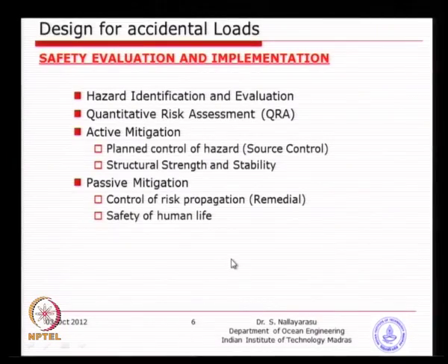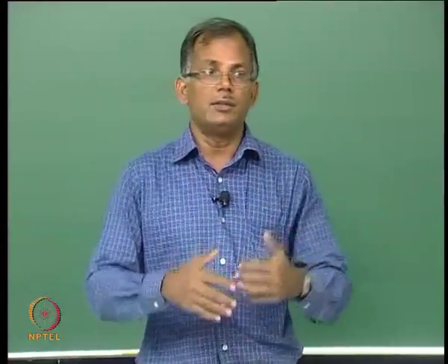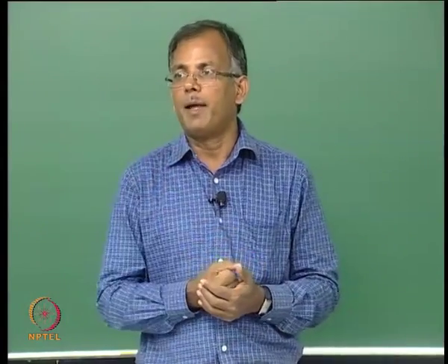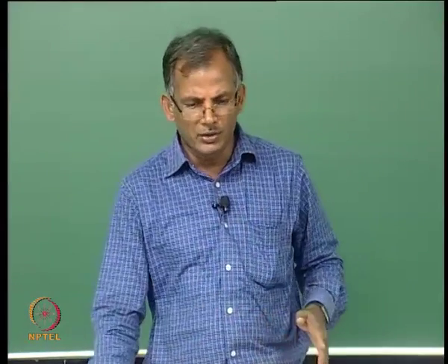And so, before we go forward towards trying to design, we need to identify the hazard. Hazard is nothing but something that is going to create or generate issues to the design activities we have carried out. So, hazard identification and evaluate them, not only qualitatively, you can say there is a fire, but what is the temperature of the fire, what is the extent of duration, what is the extent of size, and basically that gives you a feel of what could be the damage that can be done by that fire to the structure.